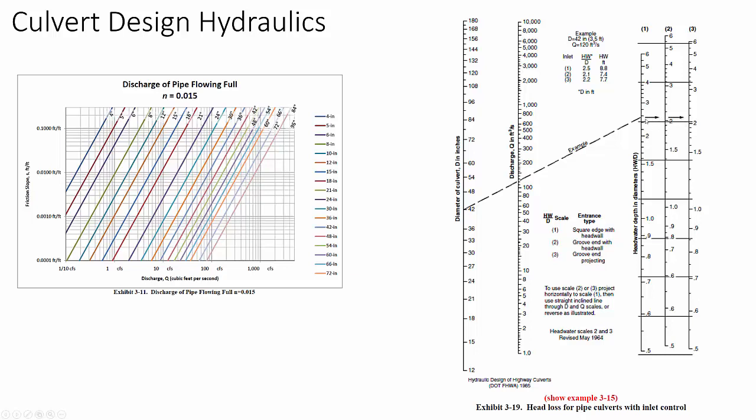I think this line should be up more. It should align with where this dashed line hits, but they drop it down to the standard width or diameters, and that gives you standard diameters in terms of D in feet. So 2.2, 2.1, and 2.5 respectively for the 3 types of head entries. So that's the way nomographs work. You've used them before in thermodynamics, certainly. So use these.